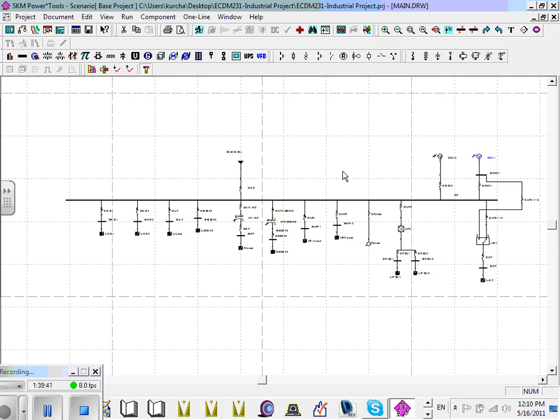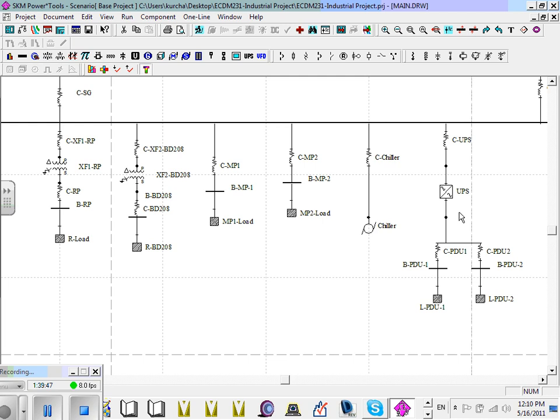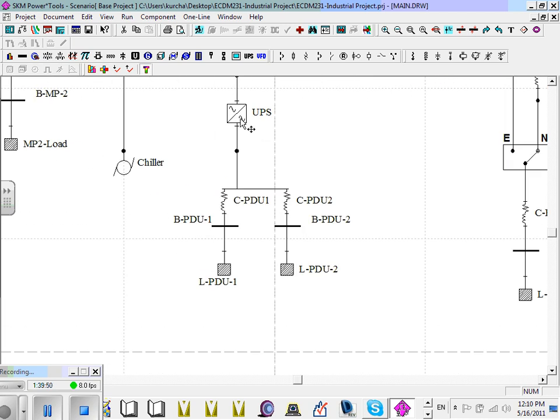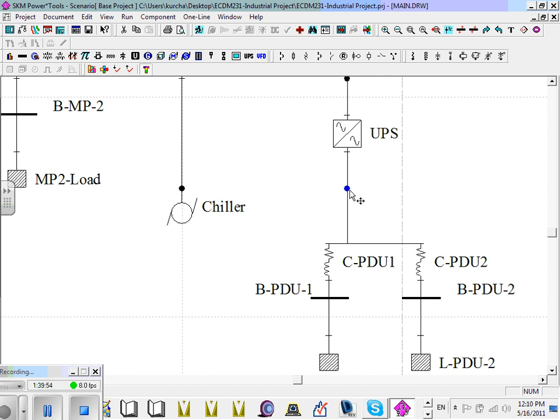Ben? I still have 40 on my UPS. On the secondary side, or the primary load side? Load side. Still Ben, the same window that you guys were doing, can you see that little dot at the bottom? Yeah. Double click on it. What does it say? 480. Change it to 208.